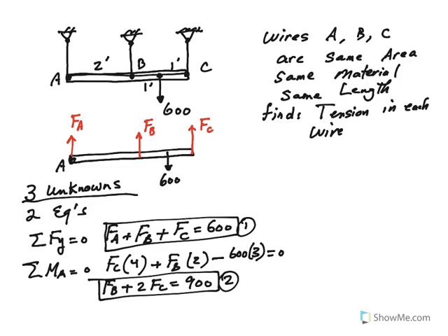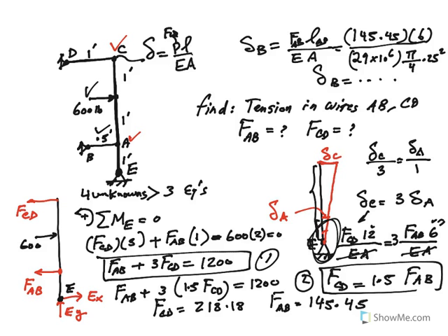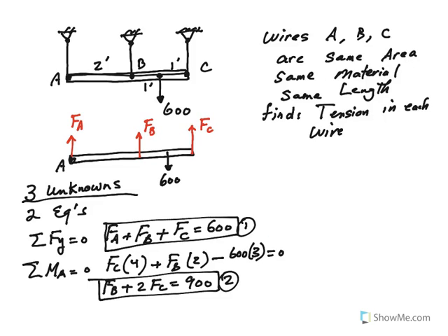But unlike the last problem, when there was a pivot point, we don't have that luxury here, guys. There's no pivot point. So now you have to say, okay, if this was the initial position of this beam, how would this deflect? Well, it would be a combination of translation. So it's going to translate down like this and then rotate. So it becomes like this.